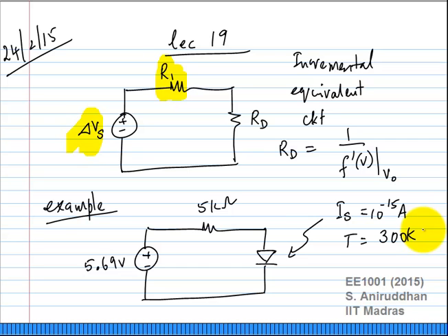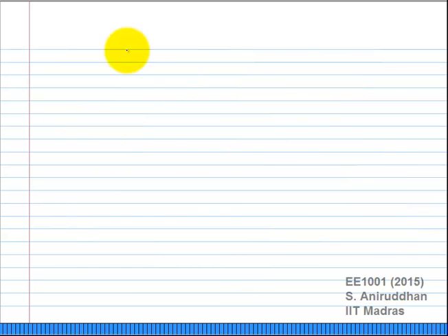Now I need to figure out how to solve this. You can put in the equation. Can somebody find out using a calculator what the voltage would be? It should be very simple. You will have to iterate even if you use a calculator. So to make things faster, I'll give you a small table, I versus V for the diode. It is just something which I drew up using a calculator for a few values.